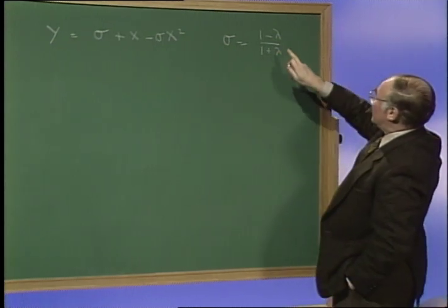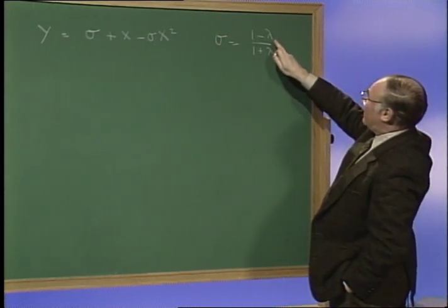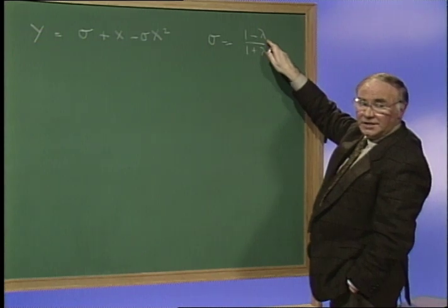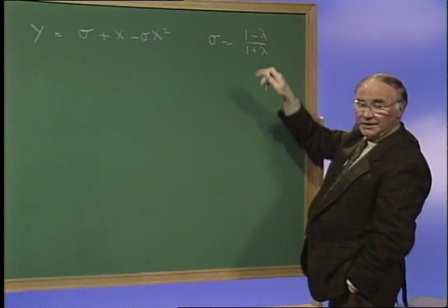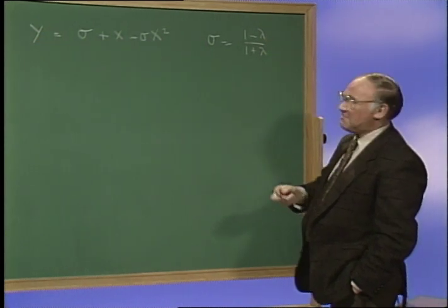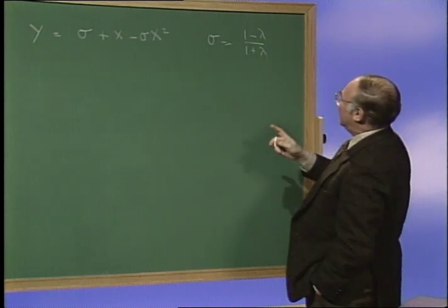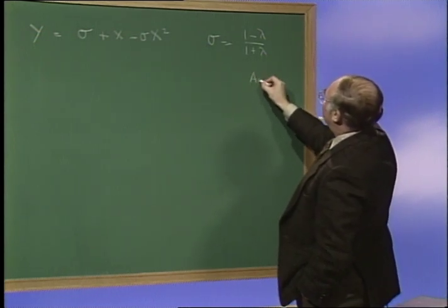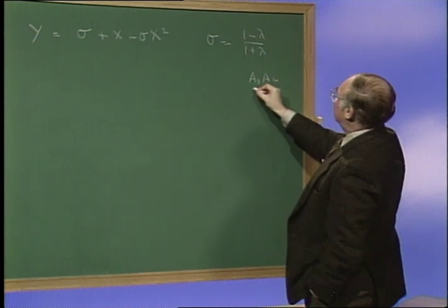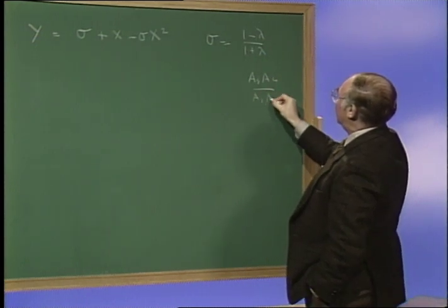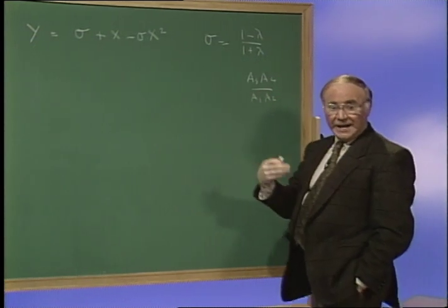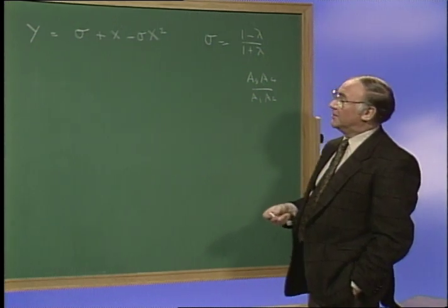It might be worth mentioning too that the area factor can be 1 even if the junctions are not the same size, provided that they're the wrong size in the right way. I think you can see what I mean. We have the product of A3, A4 divided by A1, A2, and there are numerous ways of making that 1. So we don't have to use junctions all the same size.